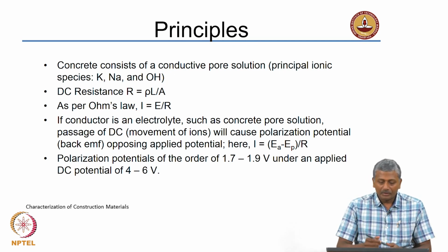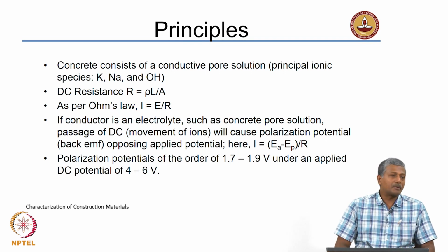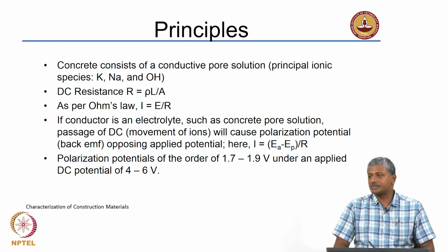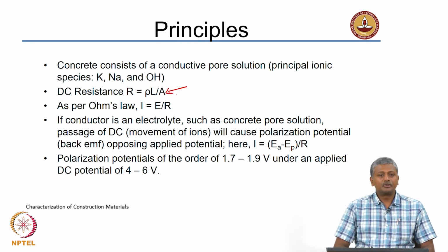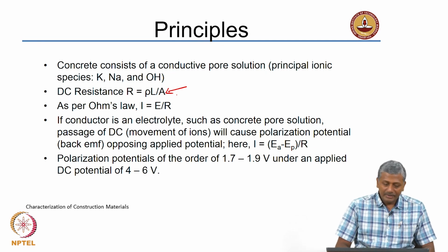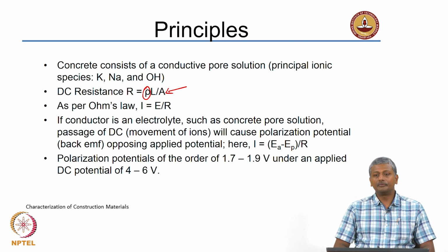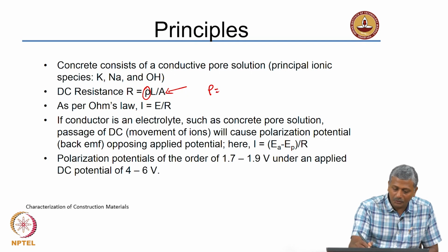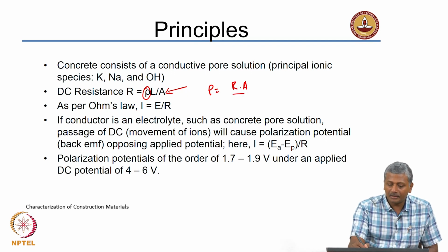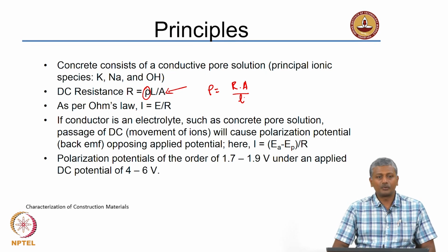Okay. So, what we generally tend to apply whenever there is electric charge transfer through a system involved is a typical assessment of the resistance to flow, right. Resistance to flow is given by a material parameter which we otherwise call resistivity, right. Resistivity is a material parameter, and of course, you also define the path of flow and the area through which the flow is actually occurring by multiplying by the length and dividing by the area, or in other words, the resistivity is equal to the resistance times area divided by the length over which the flow is actually happening.